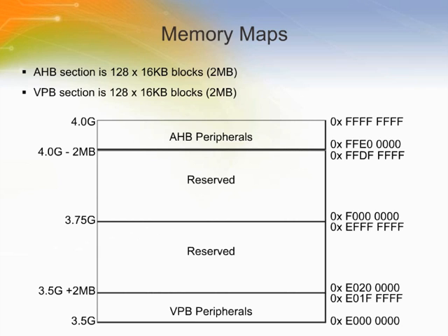The basic concept on the LPC214x is that each memory area has a natural location in the memory map. This is the address range for which code residing in that area is written. The bulk of each memory space remains permanently fixed in the same location, eliminating the need to have portions of the code designed to run in different address ranges. The MCU generates the appropriate bus cycle abort exception if an access is attempted for an address that is in a reserved or unassigned address region. The figure shows the overall map of the entire address space.